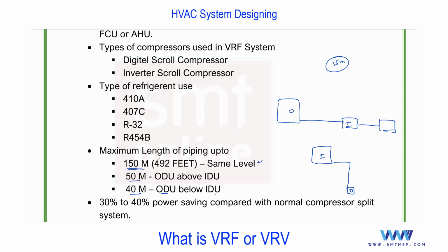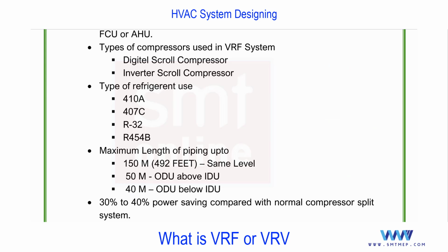Again, you need to refer to the manufacturer catalog at the time of pipe sizing, and we have a separate topic of pipe sizing for the VRF using the catalog from the vendor, or we have software also, because this is a precise or precision type of machine compared with the other type. So remember this guideline, it may be asked in an interview.